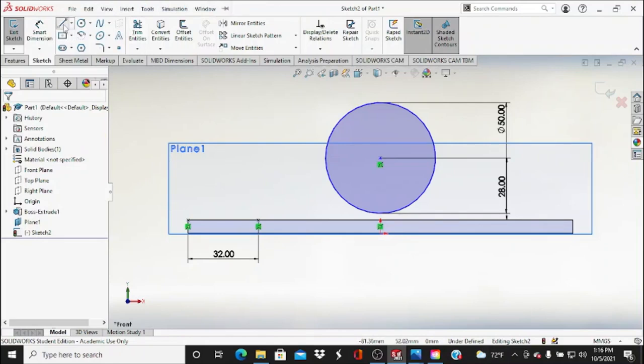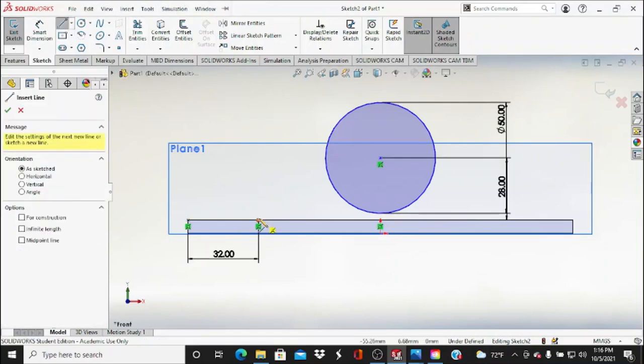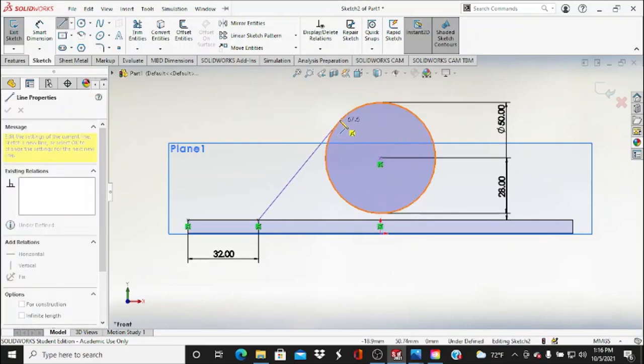32. We're going to use our line from here. Click at the point, and then we're going to make our tangent. You'll see an icon right away that changes it. Look at the pencil. There's no icon showing, but once we get to the arc or the circle, you'll see an icon pop up. You have different types of icons. One is a bit more perpendicular, and then there's another one, that's the one we're looking for, the tangent, which has a line and a circle on it. We choose that one. Right now it's perfectly perpendicular and tangent, so we click onto it.